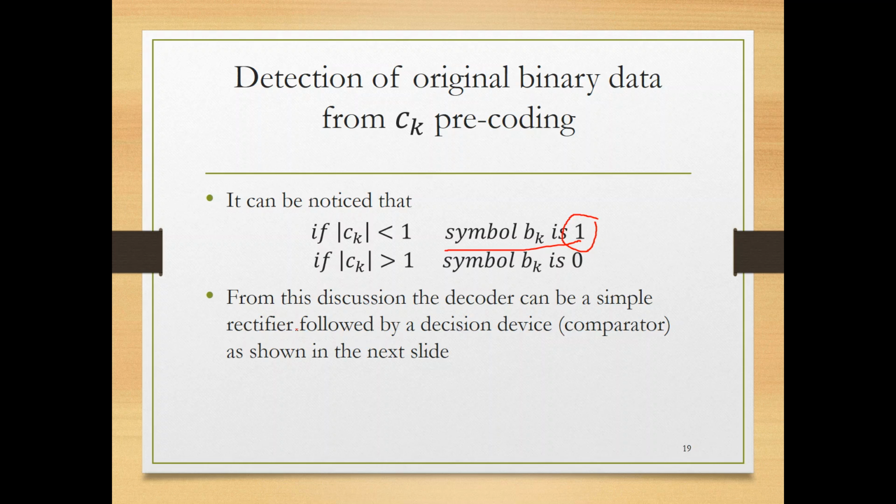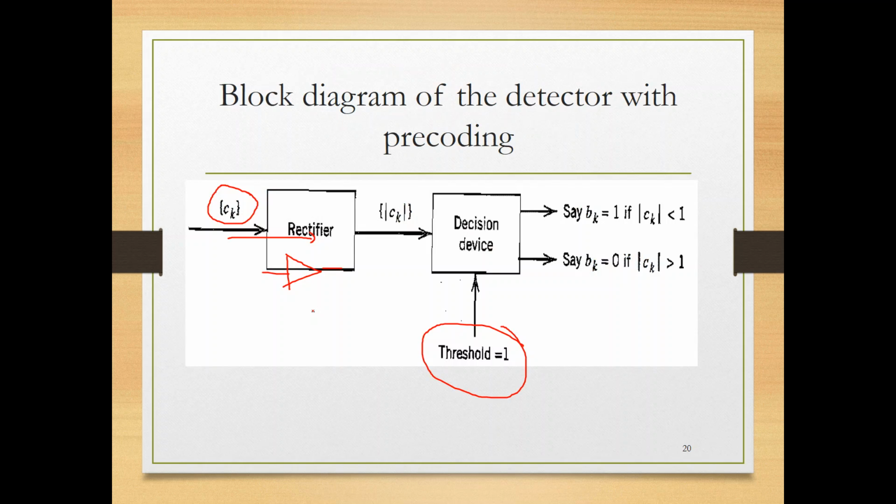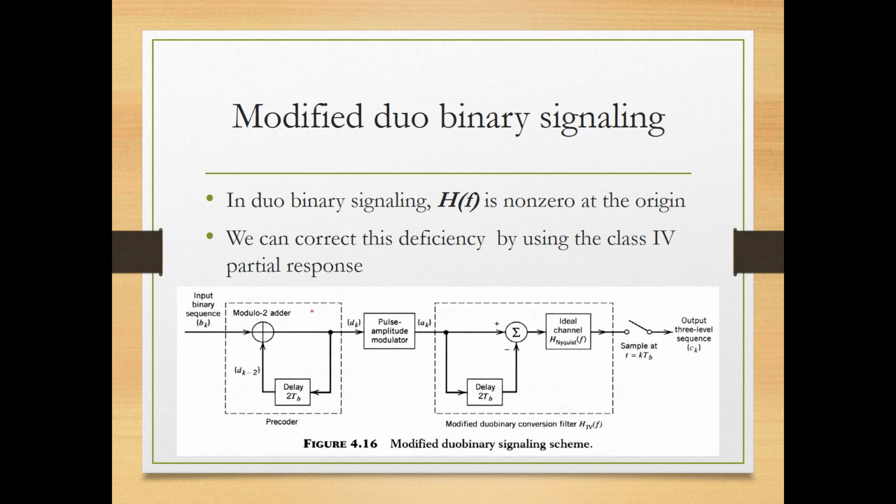You have theory in your mind, you see that this should be like this, the sequence should be, and if it's not like this, then this means that I made some errors in the detection. Clear. Then we solved the first problem, the error propagation. How did we solve the first problem, the error propagation? We solved it by using dual binary signaling. Good?